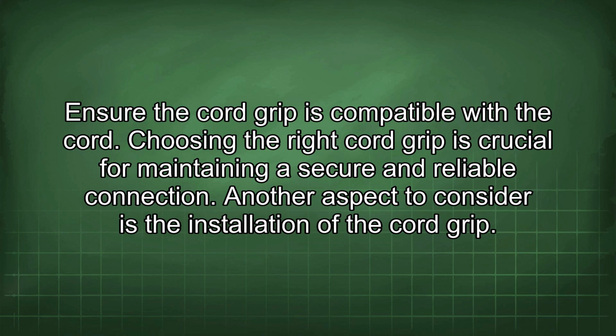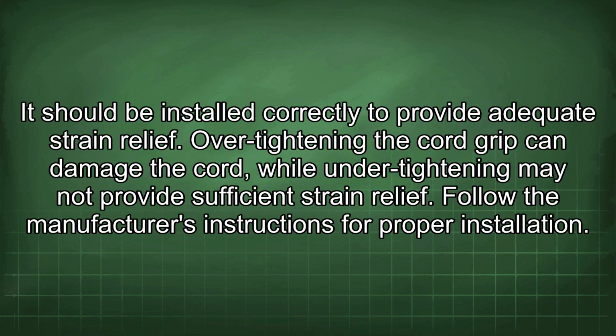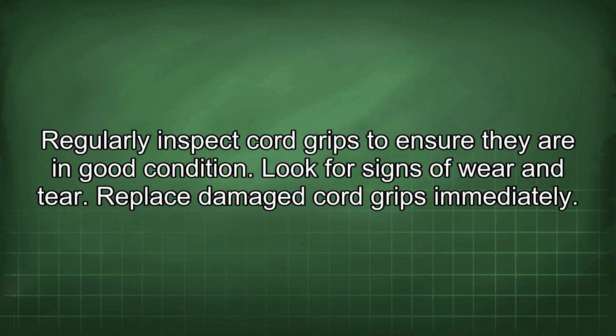Another aspect to consider is the installation of the cord grip. It should be installed correctly to provide adequate strain relief. Over-tightening the cord grip can damage the cord, while under-tightening may not provide sufficient strain relief. Follow the manufacturer's instructions for proper installation. Regularly inspect cord grips to ensure they are in good condition.